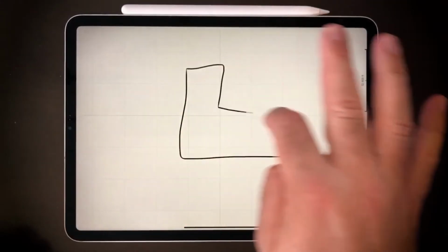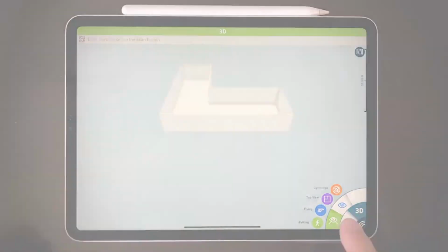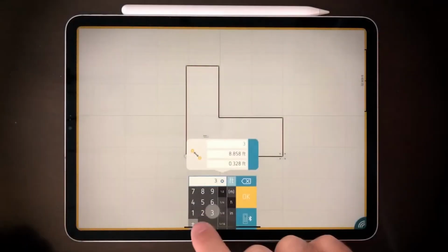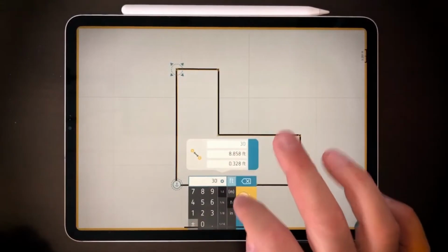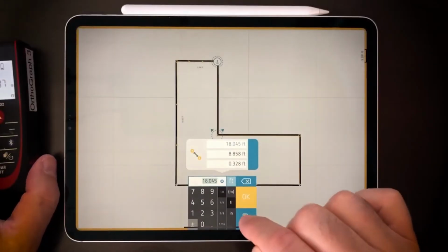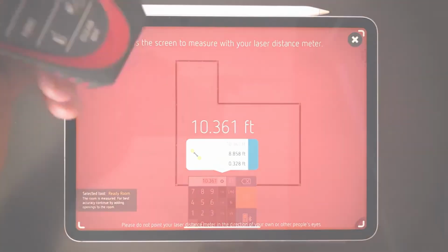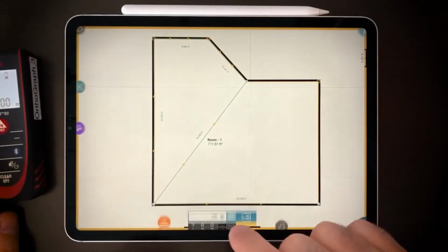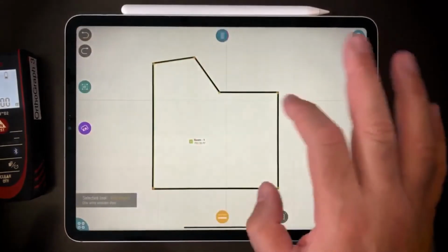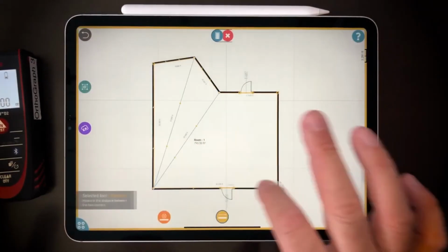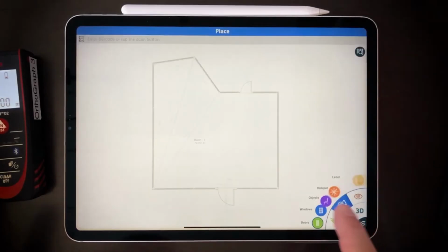First of all, making a BIM of an existing building is not that time-consuming anymore. The surveyor simply draws in what they see into a mobile app and measures the minimum required number of walls using simple tools like laser distance meters, or at a refurbishment even a tape measure can do the job. Once the walls are there and the rooms still need more details, measuring diagonals will provide a very accurate floor plan. Once the floor plan is ready, placing down and measuring doors is done with the same ease. Simply move your finger in the opening direction and measure the opening dimensions.